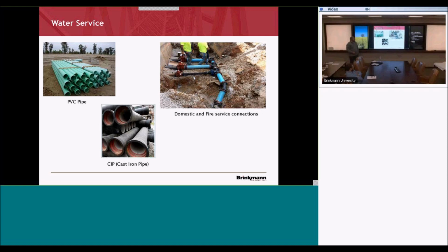One VE on the water meters. Water meters are priced by the size, so if it's like a 2-inch water meter, a 3-inch water meter, the size goes up, the price goes up as well, which means the size of the vault gets bigger, which means the cost goes up. A lot of times, if you have like a 3-inch domestic line going into your building, you can use a 2-inch water meter. They'll let you step down one size. It's something you can ask your civil, but that's usually the case on those smaller sizes, and it can save you some money.